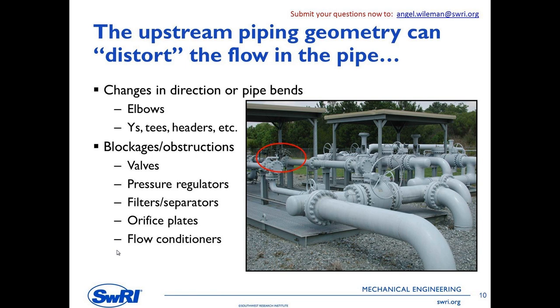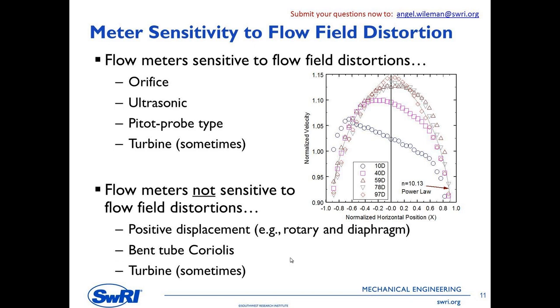Okay, so when we're talking about a distorted flow profile, what I'm talking about is if you are to look across the pipe and measure the velocity at points as you're, say, traversing across the pipe, what you're going to find is the velocity is not uniform. It's low at the wall and it's highest in the center. In this example, the bullet shape is a little bit of an extreme. That comes from an equation. Actual gas flow doesn't form a point at the tip, but it is a fairly consistent looking shape.